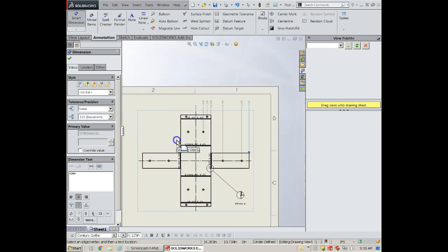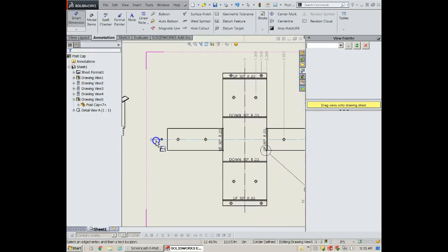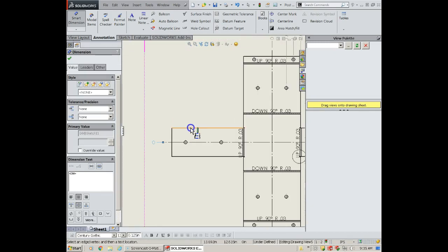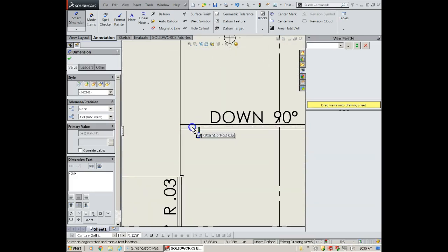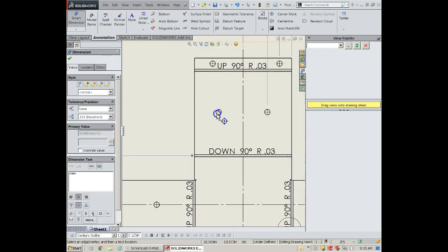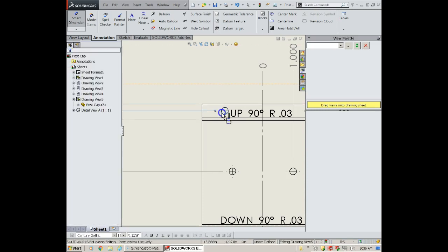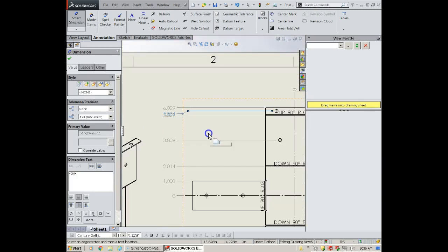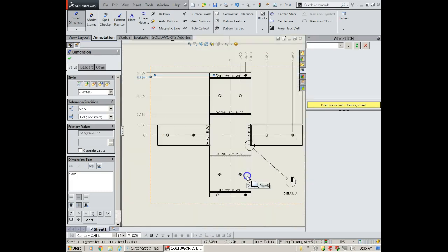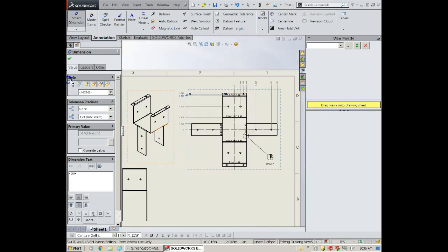We're going to do the same thing for the vertical. So we're going to hit OK, go to vertical ordinate dimension. We'll click here and then pull out all of these. Grab that bend line, this circle, this bend line, and the edge here. Oops. That guy as well. Alright. Once again, our numbers are off. I'm wondering if this part somehow got changed, but I'm going to keep moving forward, see what our other dimensions look like.